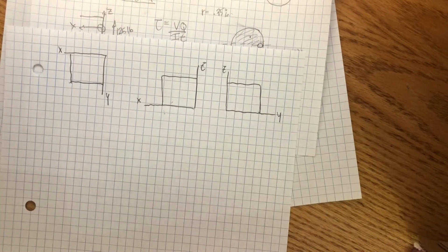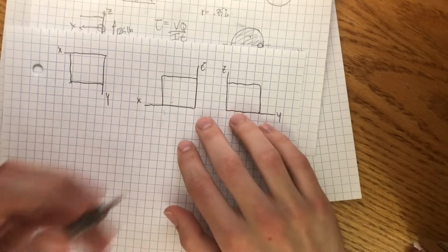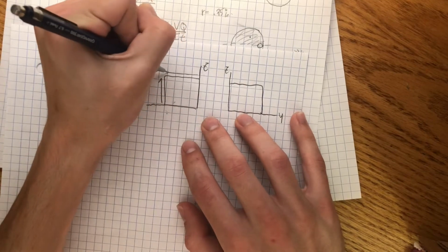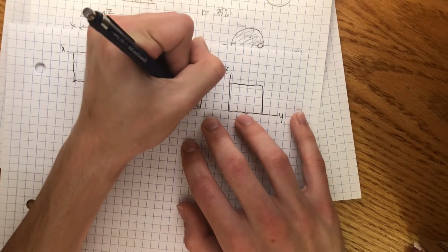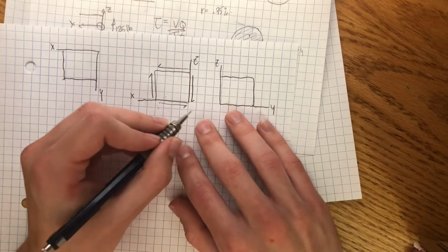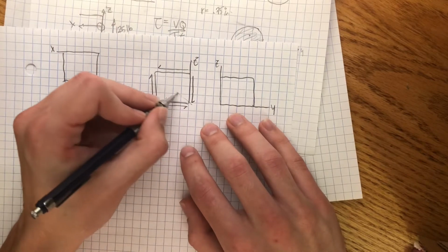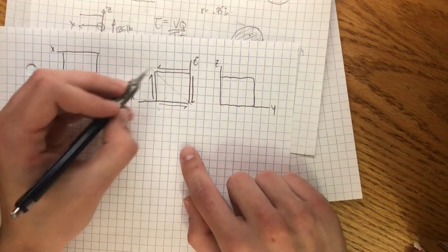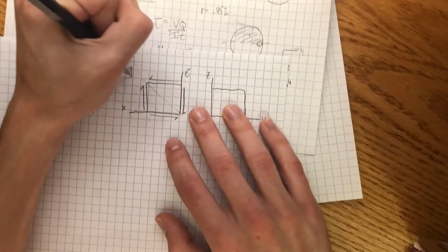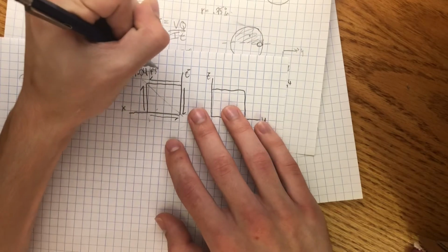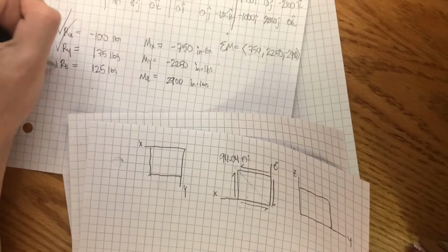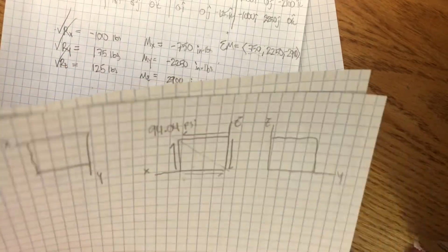So the way to do a positive shear stress is to have the line that goes from the tips of the arrows, where they meet each other, have a positive slope. In this case it does, so this is representing a positive shear stress, and it is 94.04 psi. All right, cool. So now we have done Rx, Ry, and Rz, and we're going to be moving on to the moments.